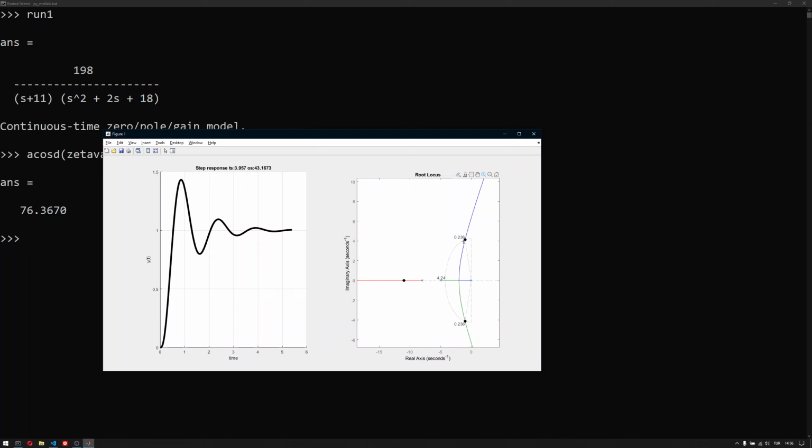And we can see that there's a circle, omega n, because if you have a fixed omega n value, you will fix the absolute value, and fixing the absolute value here, x squared plus y squared square root is fixed, so you will get a circle. So omega n lines are basically circles, the natural frequency circle, so that's basically one part of the S-grid.